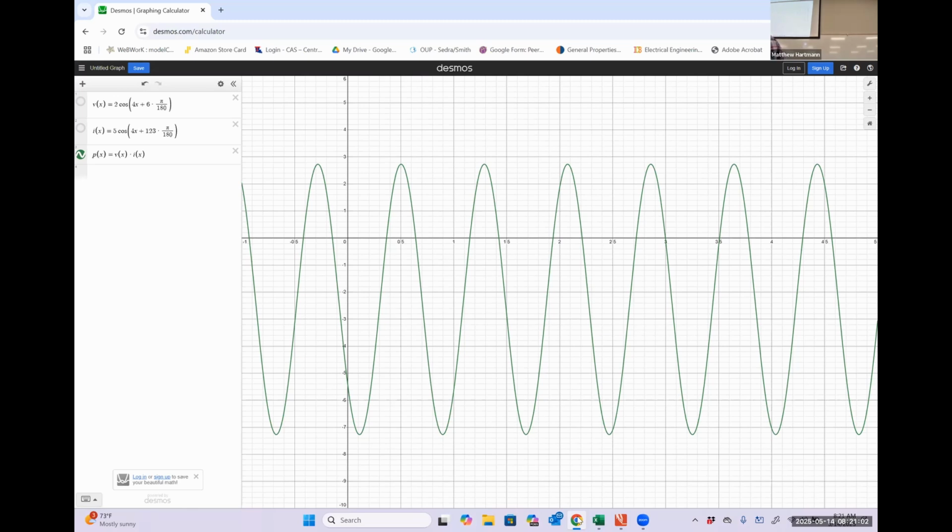Our negative peak value is relatively close to -7. So that means we have an overall span of about 10. So I think our average power in this particular case would be somewhere in the ballpark of -2 watts. Just eyeballing this graph, obviously it's going to be off a little bit, but I think it'll be just below -2 watts. So what does it mean in this particular case that our average power is negative?